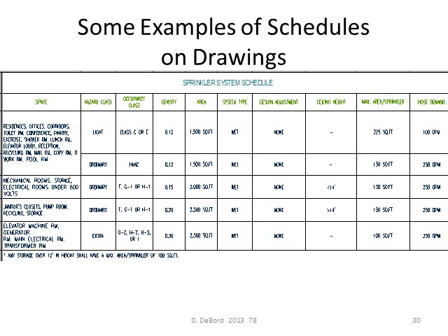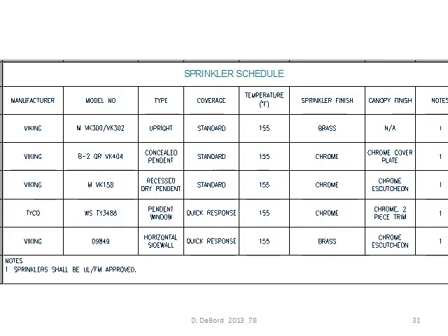The ceiling heights, notice we have less than 14 feet and greater than 14 feet listed. And then we have the maximum area per sprinkler listed, and the hose demand that would be calculated into the hydraulic calculations. This should be on your drawings, every project.